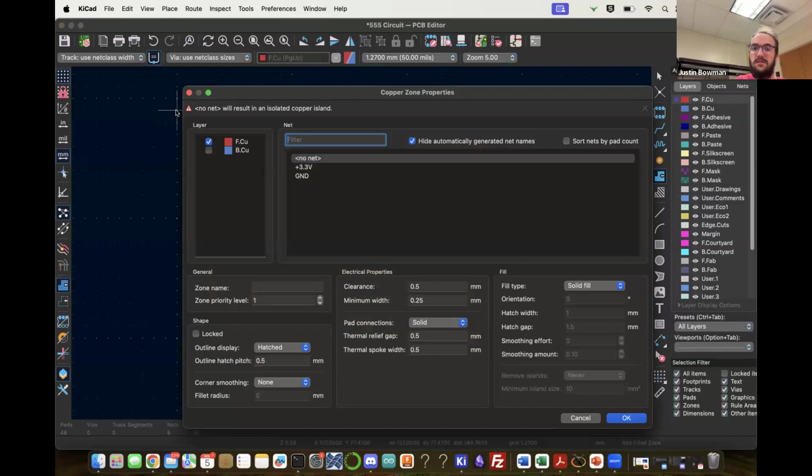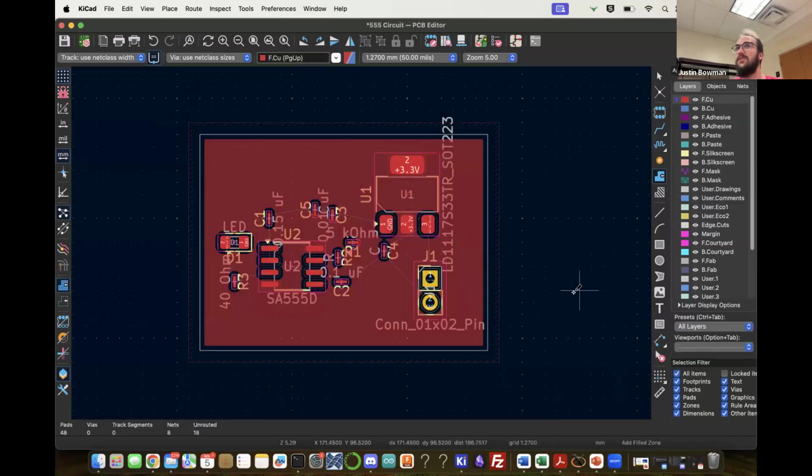You're going to decide if you... I'm going to go with ground. Understood. Okay, so you select ground, click OK, and then some lines will come off it. Then you click on a corner and basically make a square. This is the enclosed region that you want to fill. Yes. And it will automatically say if it's outside the edge cut, I'm not going to fill it.